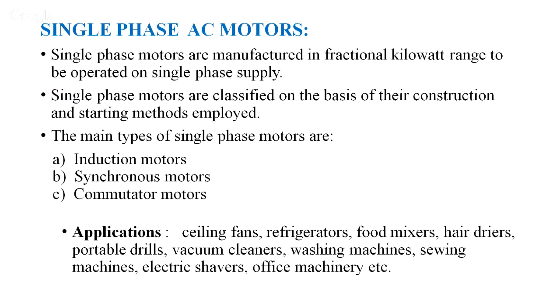Single-phase AC motors. Single-phase AC motors are manufactured in fractional kilowatt range to be operated on a single-phase supply. These motors are classified on the basis of their construction and starting methods employed. The main types of single-phase motors are induction motor, synchronous motor, and commutator motor.